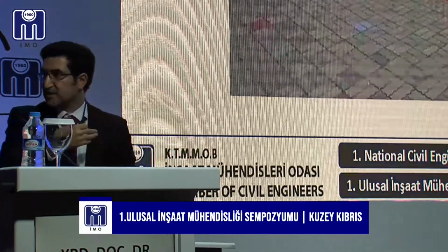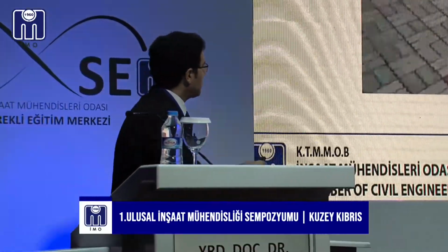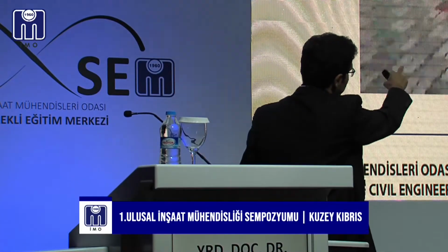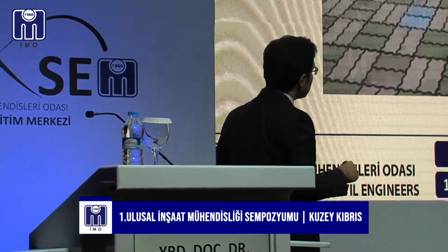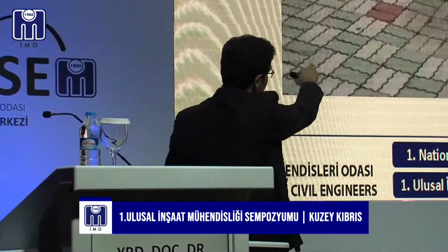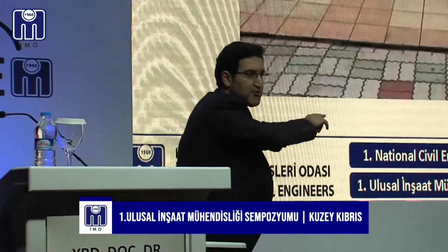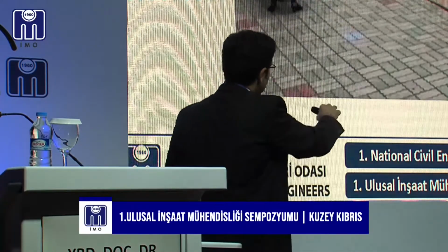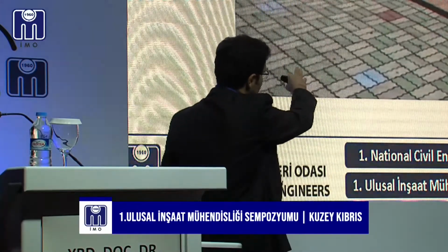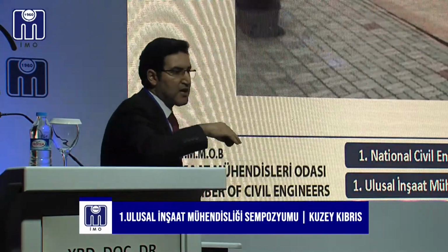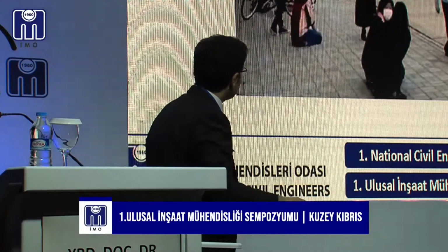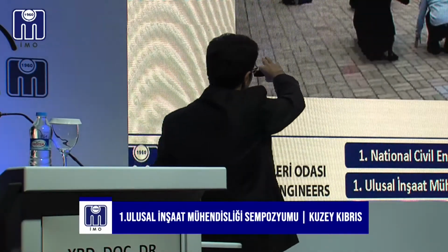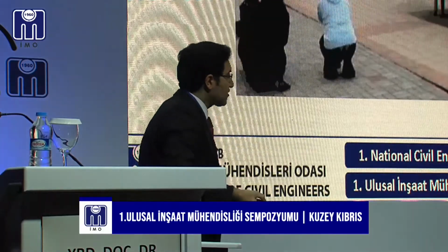For the last one, please, I want to show you the liquefaction on the ground. If you pay attention to this one, during the 2011 earthquake, we have shaking on the ground, as you can see. And after 40 seconds, we can see sand boiling on the ground surface. So this is the shaking, and after that, pore water pressure builds up, and after the pore water pressure builds up, you can see the sand boiling and water coming out of the ground.